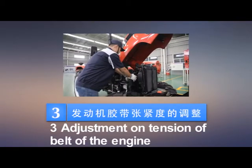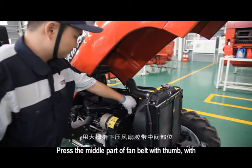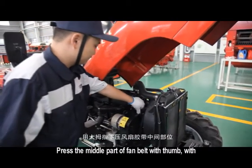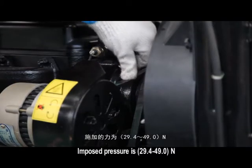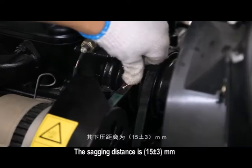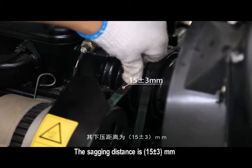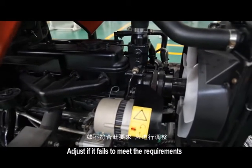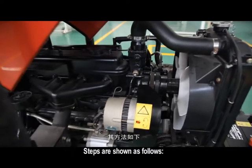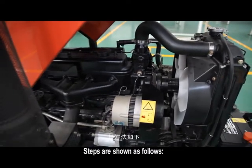3. Adjustment on tension of belt of the engine. Press the middle part of fan belt with thumb width. Imposed pressure is 29.4 to 49 N. The sagging distance is 15.3 mm. Adjust if it fails to meet the requirements. Steps are shown as follows.